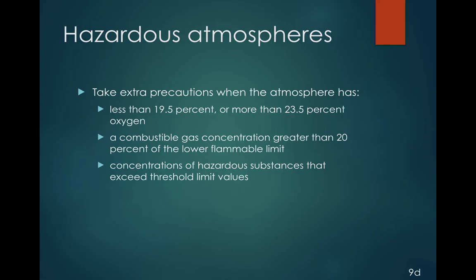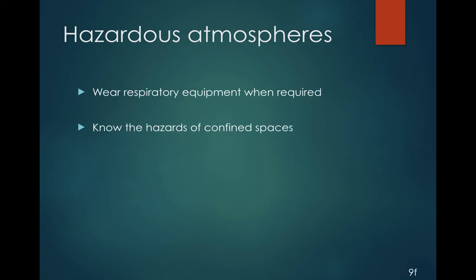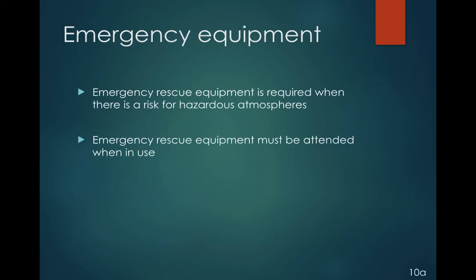gas concentration greater than 20% of a lower flammable limit, and concentrations of hazardous substances that exceed threshold limit values. Conduct all operations within OSHA requirements. Regularly conduct atmospheric testing if atmospheric hazards are present. Wear respiratory equipment when required, and know the hazards of the confined spaces.